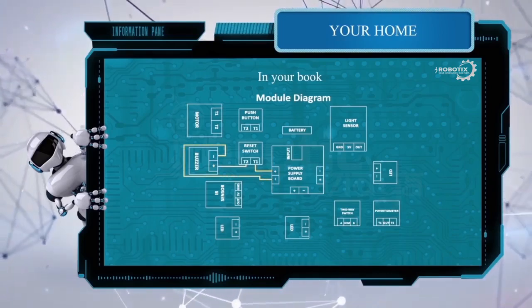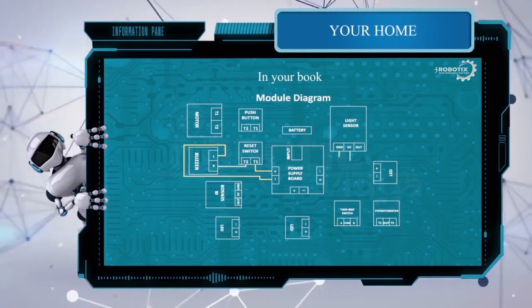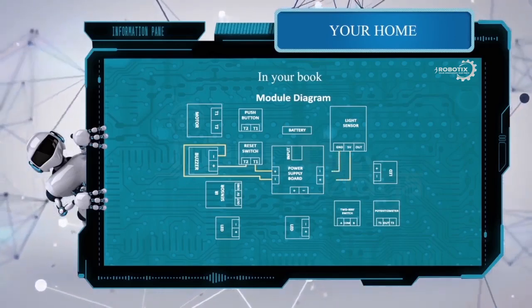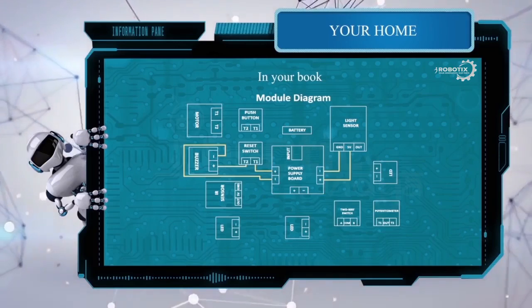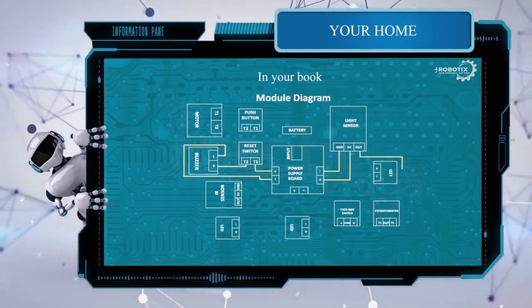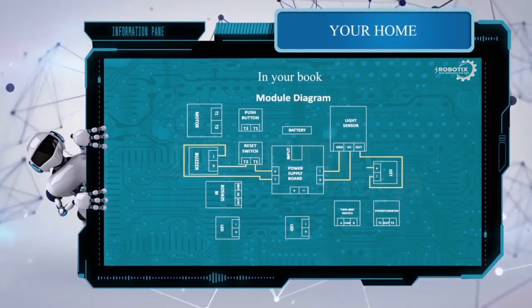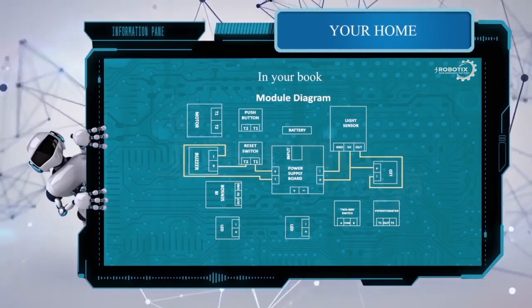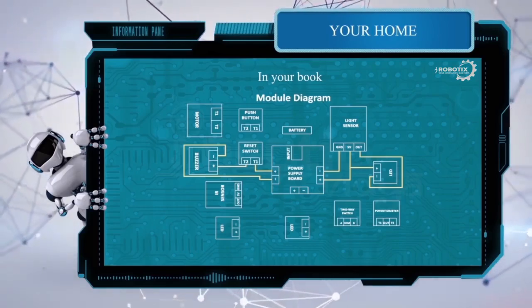The next one is your automatic outdoor lighting. So first, start off your plus and minus being given to your sensor 5 volt and ground respectively, and the output of your sensor is given to the LED negative, and the LED positive comes back to your power supply board's positive. The next one is your presence lighting.